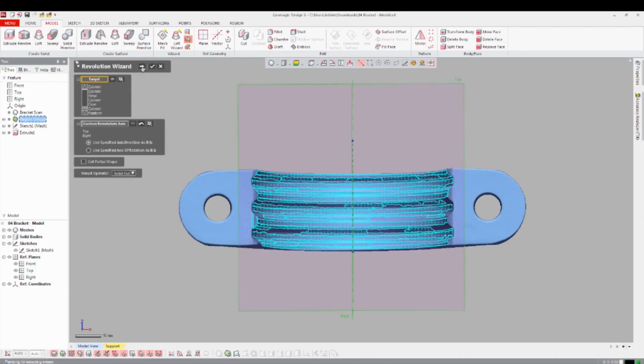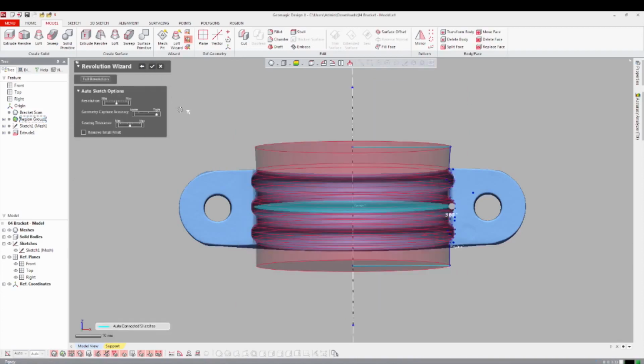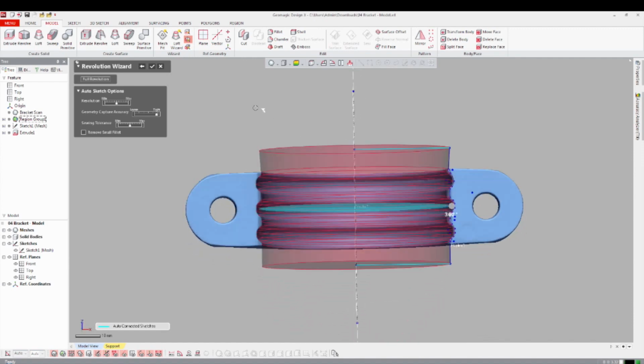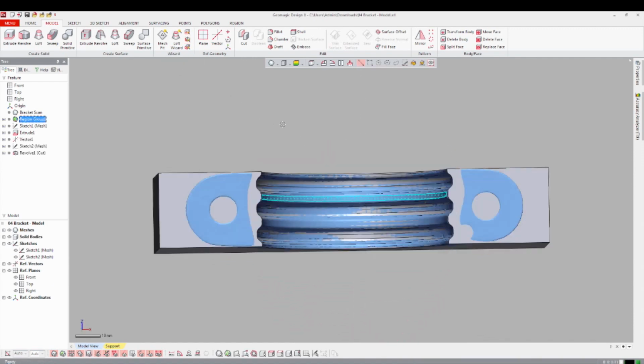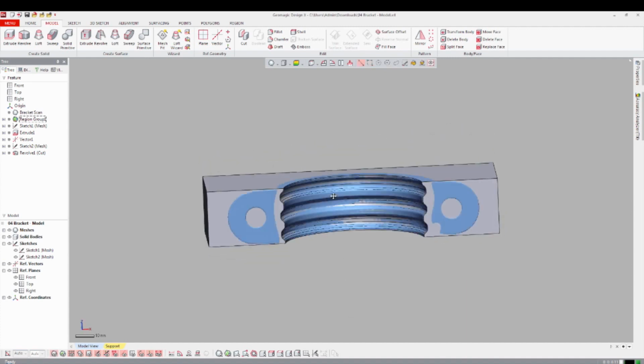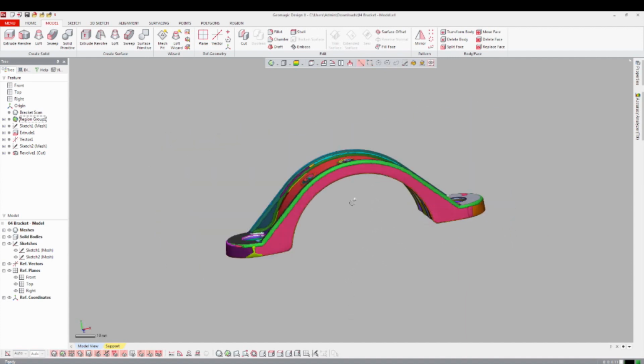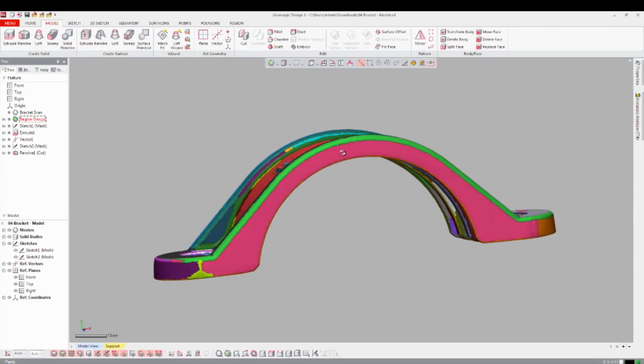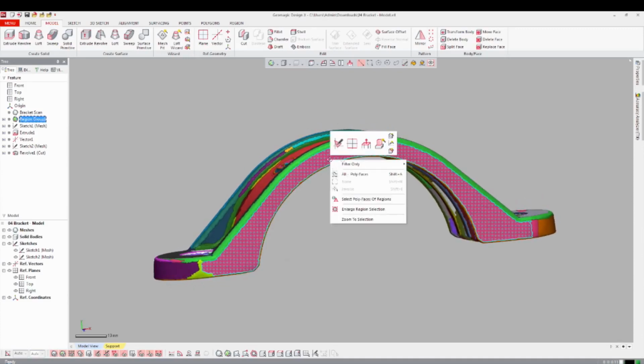Now select Next Step to preview. If it is correct, hit OK to apply. You will now see the bracket solid starting to form. Go to the Extrusion Wizard again and select the top edge surfaces as well as the front region.